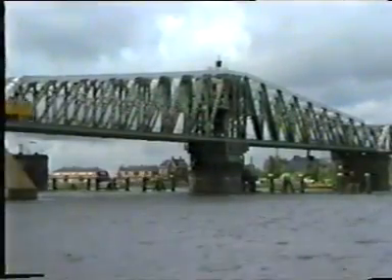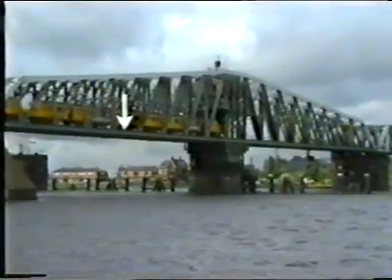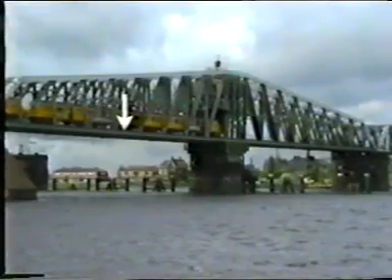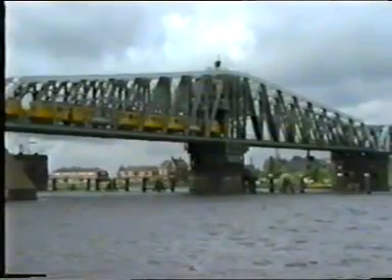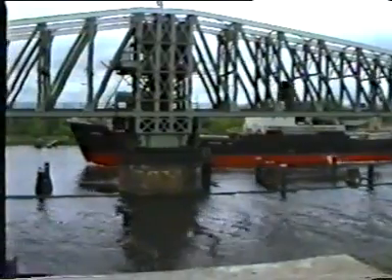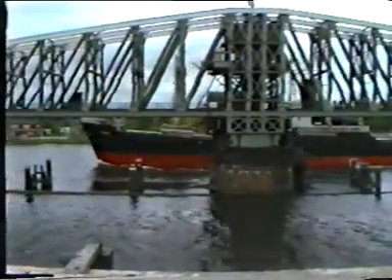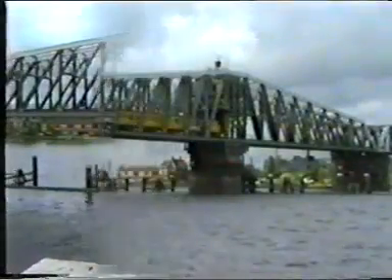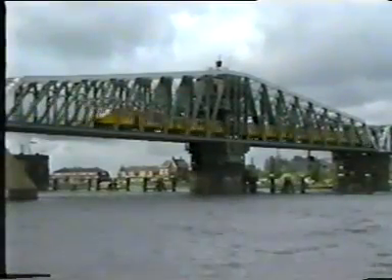A rim bearing changes the swing bridge in service condition into a girder on 4 supports, of which the central span is relatively small. Loading on one leaf introduces an upward deflection of the other leaf, and the reaction on one support on the pier may reduce to 0. To prevent this, the central part is equipped with a light truss system, which allows shear deformation to occur. In this way, the bridge rests on all supports, even if unequal loading is applied.